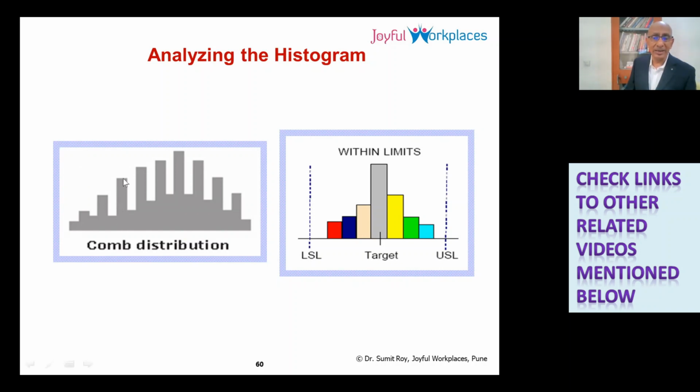Actually, the moment you are getting a particular data, what I'm trying to do as an operator is that I find there is some error in my measuring equipment. What should ideally have gone here in this class is being approximated by the measuring instrument to the left side. That means I am using a lower accuracy measuring instrument, and based on that I am putting down the reading.